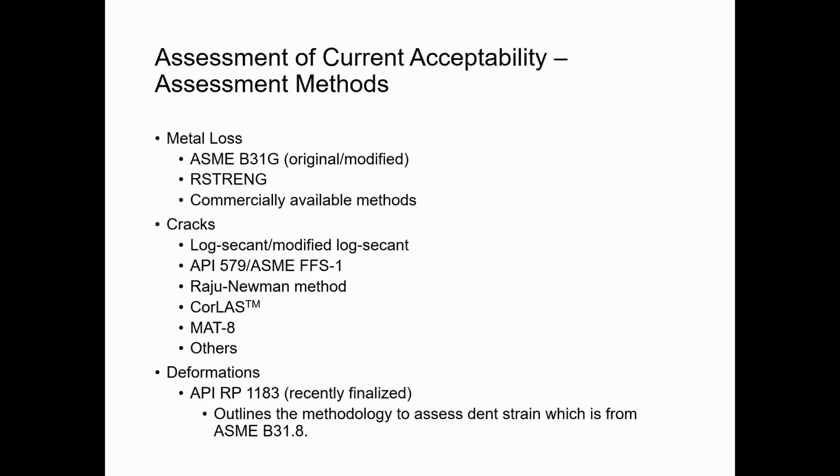Regarding deformations, there's a recommended practice by API that just was recently finalized, 1183. It outlines the methodology to assess dent strain, which is from ASME B31.8.